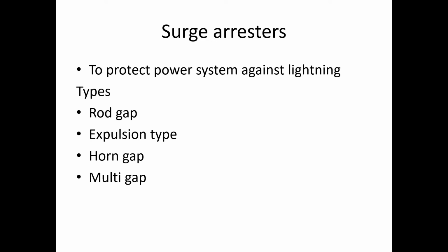We all know that we use it even in our households to protect household appliances and equipment, and it may be used in tall buildings. There are certain requirements for the lightning arrestor which we should consider during the selection process. The lightning arrestor should not pass any current to the system component even during abnormal condition. During normal or abnormal condition, it should not pass any current or over voltage to the equipment which is to be safeguarded. During abnormal condition, it should not break down. Moreover, it should have very high stability.